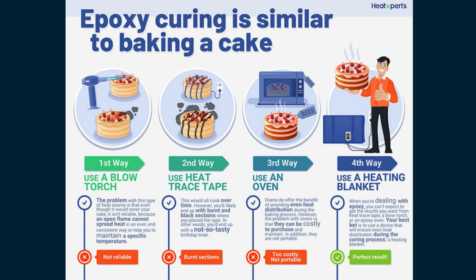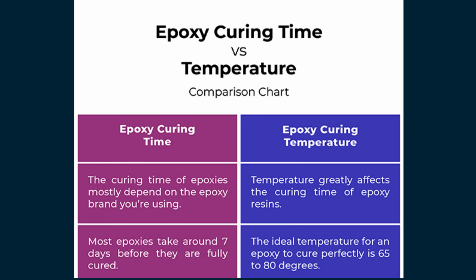Catalytic curing systems such as tertiary amines, boron trifluoride complexes, imidazoles, and dicyandiamide enable homopolymerization of epoxy resins and are particularly useful in one-component adhesive systems with extended shelf life. Finally, polymercaptans provide extremely rapid room temperature curing, making them suitable for quick-setting adhesives despite their limited thermal resistance. Understanding the chemical behavior and processing characteristics of these curing systems allows materials scientists and chemists to tailor epoxy adhesives for a broad range of industrial applications, from low-temperature bonding to high-temperature structural materials.